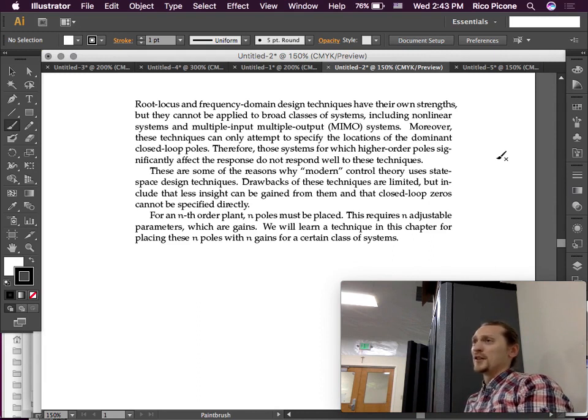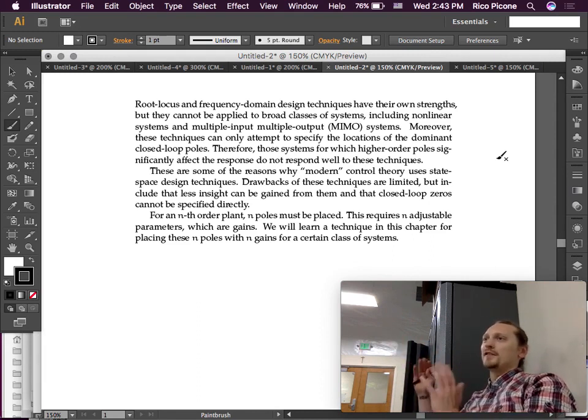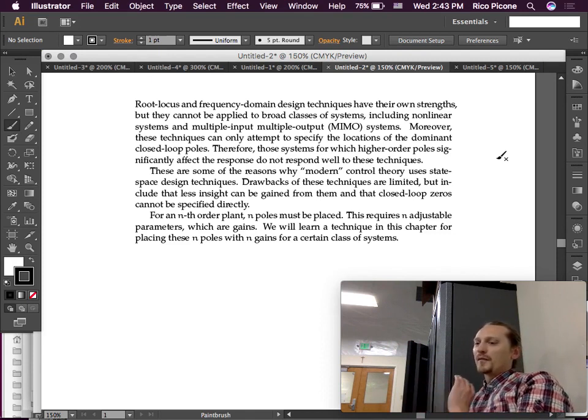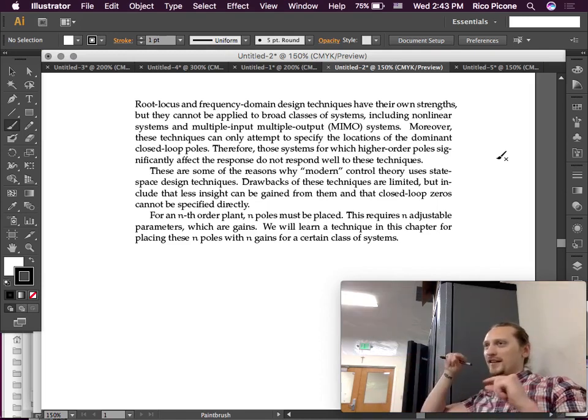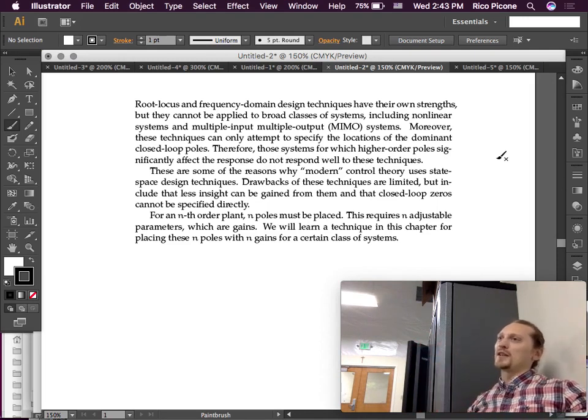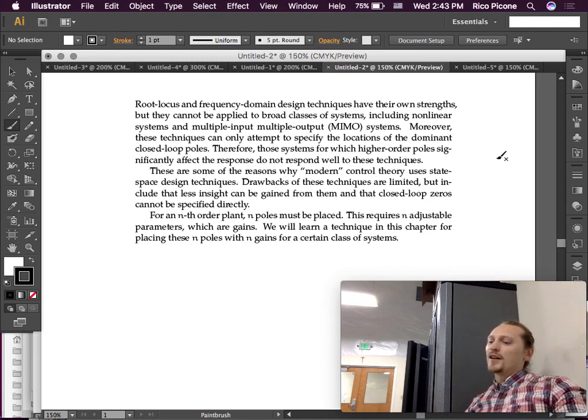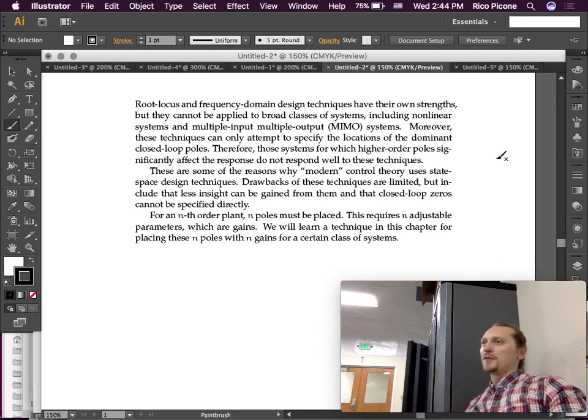So it's pretty easy. You can just put AX plus BU in the function file. But then in that function file, at every time step, you can limit your input. So you can essentially open it up and tweak things at every time step of the simulation, whereas you can't do that in LSIM; it doesn't give you those hooks. But if you use one of the ODE solvers directly, then you can hook into it and limit values artificially, or you can create all kinds of weirdness if you want to. So that's how to do it at every time step.